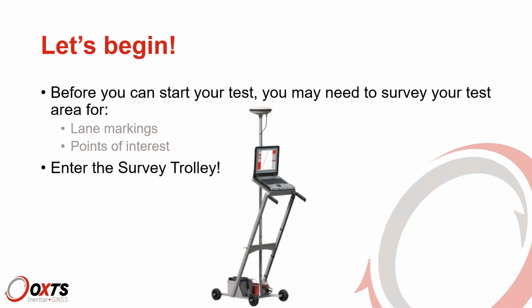So let's begin. Before you can start your test, you may need to survey your area for things like lane markings or points of interest like traffic cones or traffic lights, road signs, anything that the sensors on your vehicle might be trying to pick up that you want to validate that they are picking up at the relevant times.